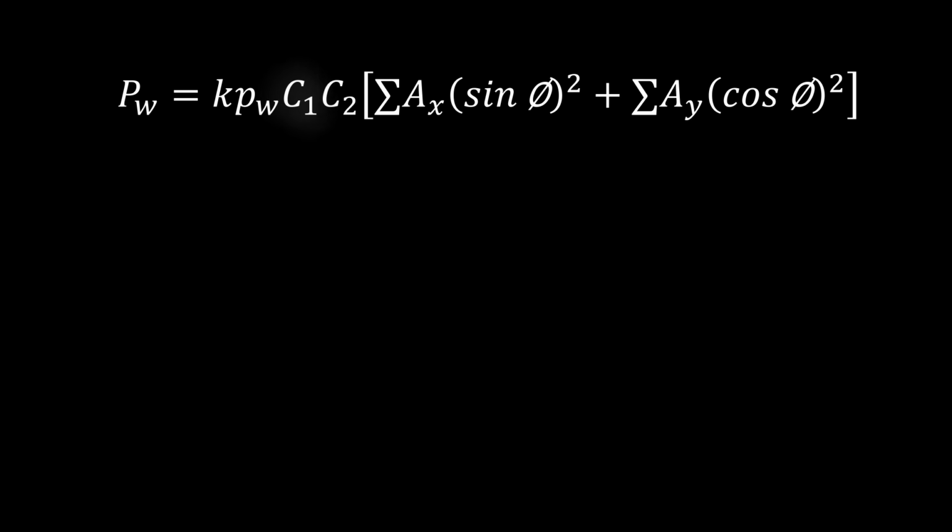of larger vessels. In addition, a gust factor is introduced to account for the dynamic amplification caused by wind fluctuations over time. A shape factor is also included to account for aerodynamic effects, such as suction on the leeward side of the ship, which can significantly increase the total force.